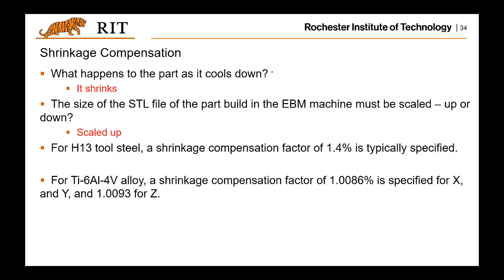Also, there's a shrinkage compensation that needs to be done when you do the design, because when the part cools down, it will shrink. If you design your part at the scale you want the final part to be, it will shrink to a smaller size.